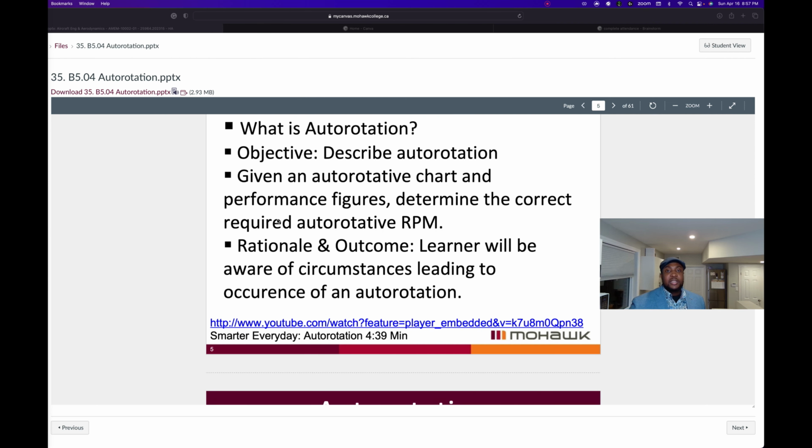During steady state descent, the airflow is now flowing up through the rotor disc. So this is during autorotation. The blade angle remains unchanged, yet the angle of attack is increased. So this is where we get that advantage. Because we've lowered that collective lever, it's unfeathered the blades in such a way that the direction of flight is now facing downwards, and as such we have additional lift being produced by that flow.